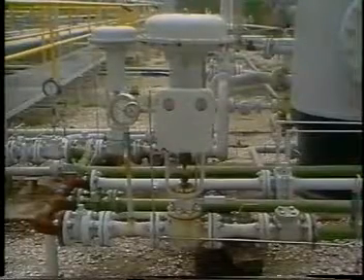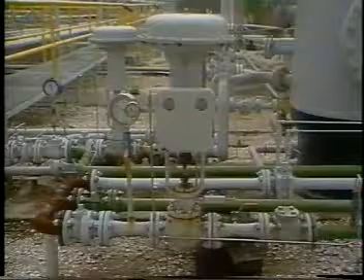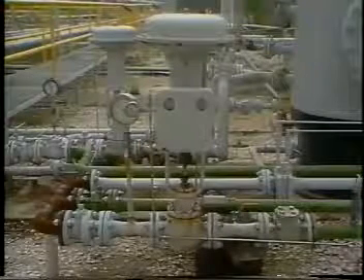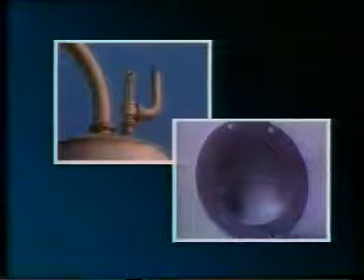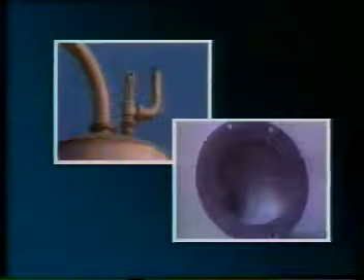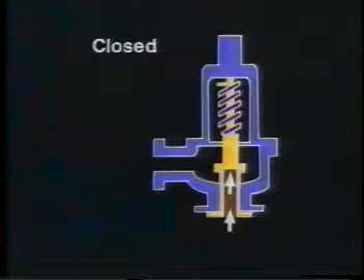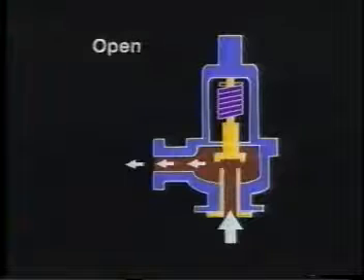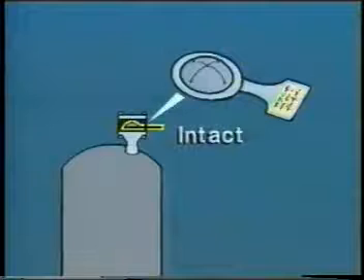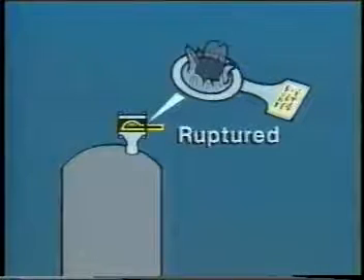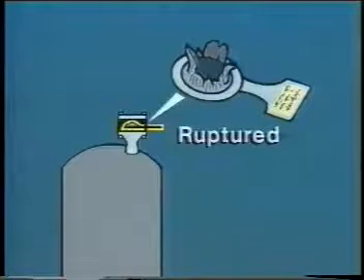If these valves fail to work properly and the pressure begins to build up in the separator, relief mechanisms are relied upon to avoid rupture of the vessel. Pressure relief valves and rupture discs are used to provide an emergency vent should some malfunction cause the vessel pressure to rise to a dangerous level. Pressure relief valves are set to open at a pressure above the normal operating pressure. Rupture discs are metal discs designed to split open when a certain pressure is achieved. These discs must be replaced when ruptured, while relief valves can open and close repeatedly.